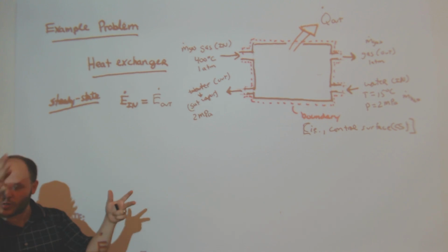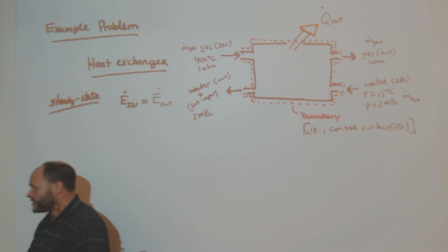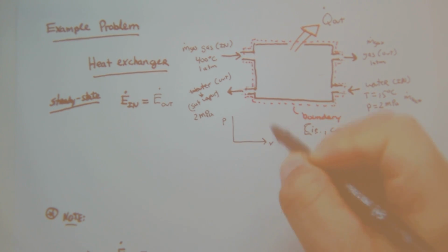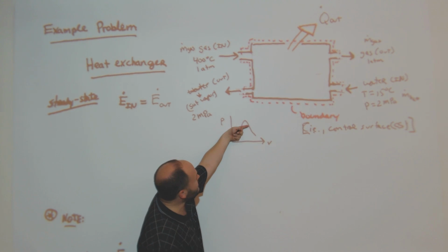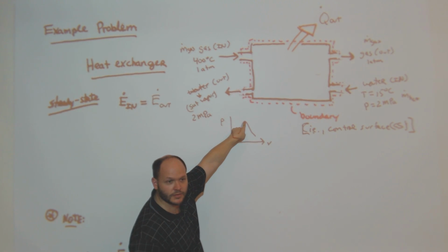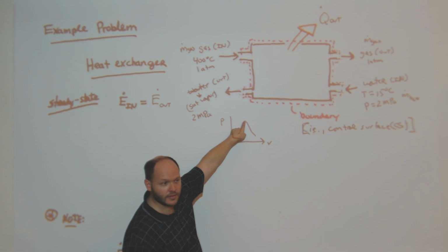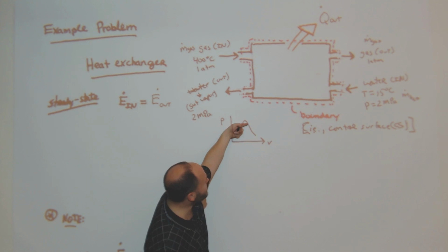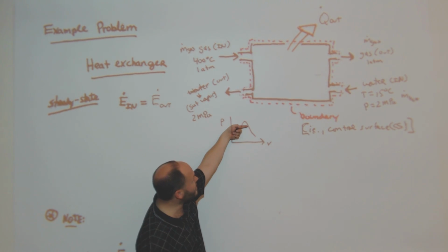Now, of course, you can also draw the bell curve and you can figure this stuff out, right? So if I were to draw a bell curve, I can just do that here. And let's just say pressure, specific volume for water. As I progressively go up, I reach the critical temperature where you can't distinguish between water vapor and liquid water. That's really high, 600, right? Some degrees Kelvin for water. But each isobar is a higher temperature. Now I could change this to temperature here and specific volume, and then each one is an isobar at higher pressure.